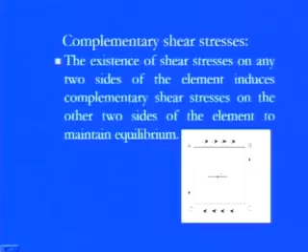Like you see here, if we have chosen AB and CD, on which tau is acting, the shear stress is going across them as parallel forces, as I told you. They are going in these directions, so they will tend to move this object in the clockwise direction. So we require an opposite component to compensate or resist this motion.